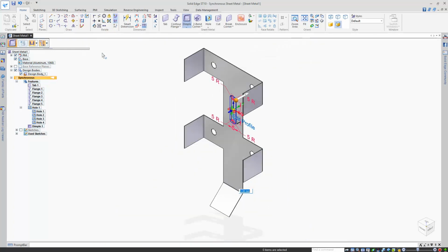Sheet metal parts often have sharp corners on them, and best practice is to break or round them off for safety reasons. In this case, I want to add fillets to each corner in the model. And if I wanted to do so individually, I could, but instead, I'll fence select all the corners that I want to break. And instead of 10mm, I think a 5mm break would be more suitable.